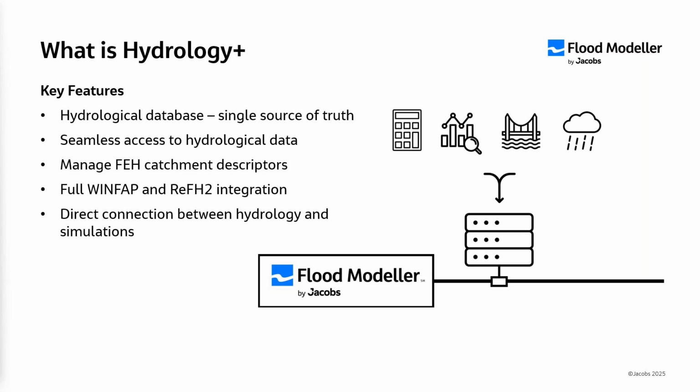So after you have created a Hydrology Plus project, you can import and manage FEH catchment descriptors. You can perform hydrological analysis by opening WINFAP and ReFH2 from within the Flood Modeller UI. So WINFAP and ReFH2 will have to be installed on your machine separately.